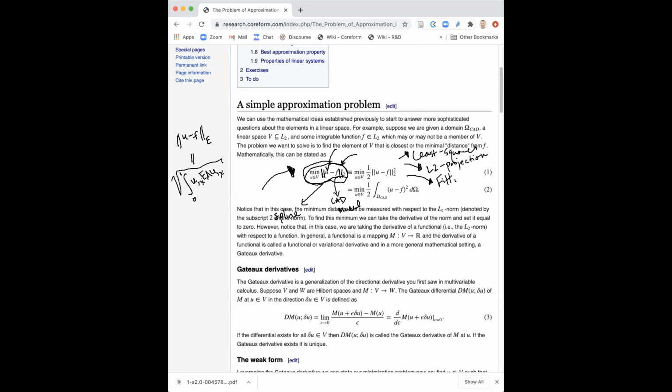Okay, do you see this? This right here, guys, is just a bar being pulled by some force F. And then U comma X is nothing more than the strain. And EA U comma X, this is the stress. So strain, stress. Put 1/2 out here. So this guy right here is the energy of a bar in tension, where F now is an applied load.